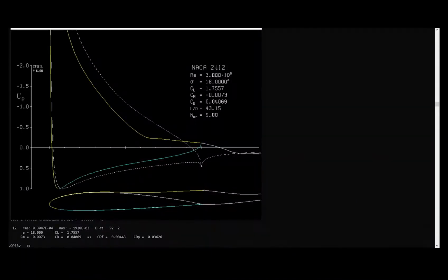And look at that, we have the performance at a very dramatic angle of attack. Notice how the boundary layer grows much more rapidly, and at some point, flow detaches completely from the foil. Generally, you want to avoid this massive separation because it comes with a very high drag penalty, which is why you generally don't try and fly NACA 2412s at 18 degrees angle of attack.